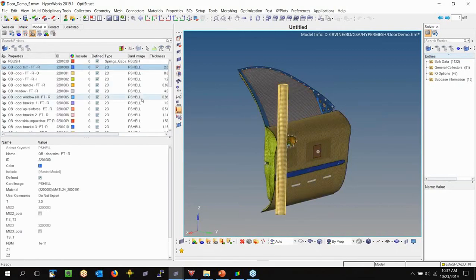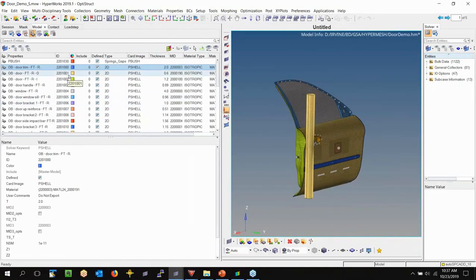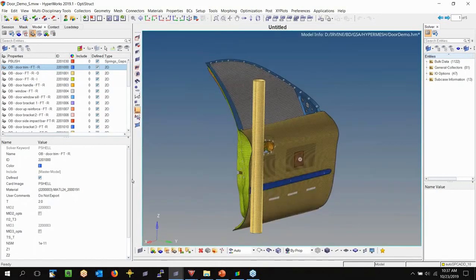And then in terms of properties, the property definitions are linked from the material. As you see, if I start looking at any of these properties here, they already have assigned materials, and then you start defining thicknesses, the properties of beams, stiffness of bushes, etc. So that gives you a comprehensive step-by-step flow from a part definition to moving into a material and property.